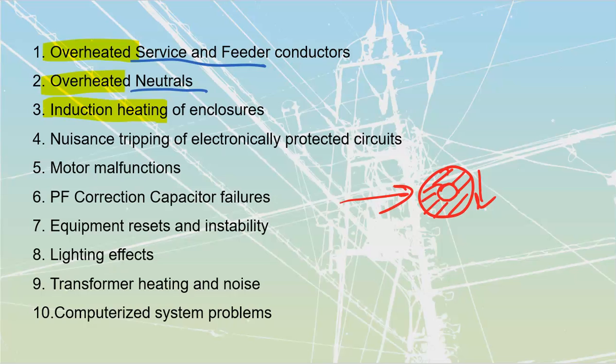Not only are we going to have overheating of the cans, we're also going to have overheating of other associated components like the cores. Magnetic cores inside of transformers, things like that, are made out of metals that just do not react well to that 120, 180, etc. for my frequency. So we don't want to see any of that stuff heating up, especially around anything that's got windings, motors, transformers, etc., because it starts to cook off the insulation. Right? We get the degassing, we lose the VOCs, and we can start to lose those transformers.